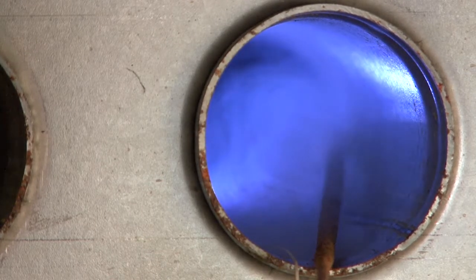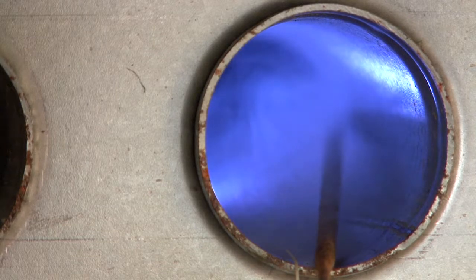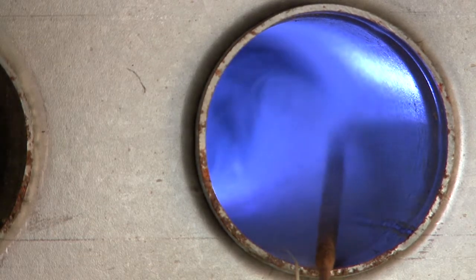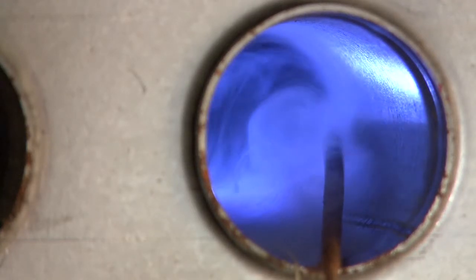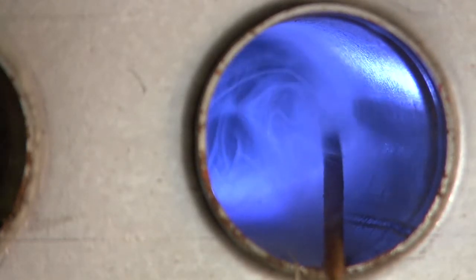Now, if you've got an impingement, again, it could actually suck the smoke away from you, or it could blow it right back at you. And as you can tell from what I'm doing with this one here, there is no problem in the cell of that heat exchanger. Now, we do want to repeat this process through each tube of the heat exchanger.